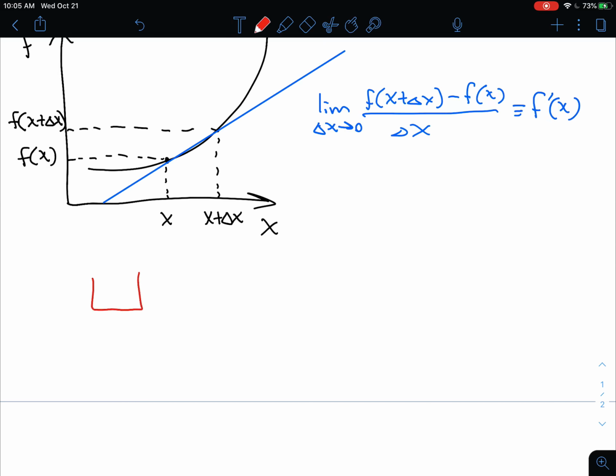I'm going to start with a material balance on stream 2. If I have a flow rate F2, and presumably that has units of volume per time, let's say liters per hour, and I have a certain density, then I can calculate in some increment of time what amount of fluid would enter my control volume.